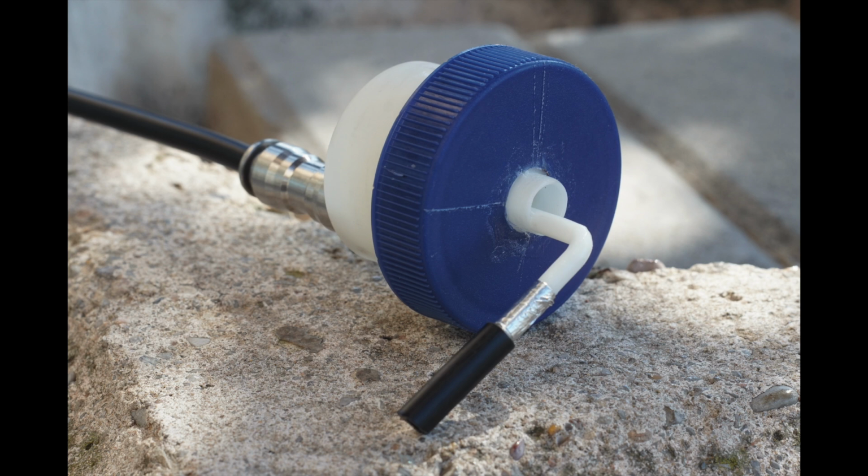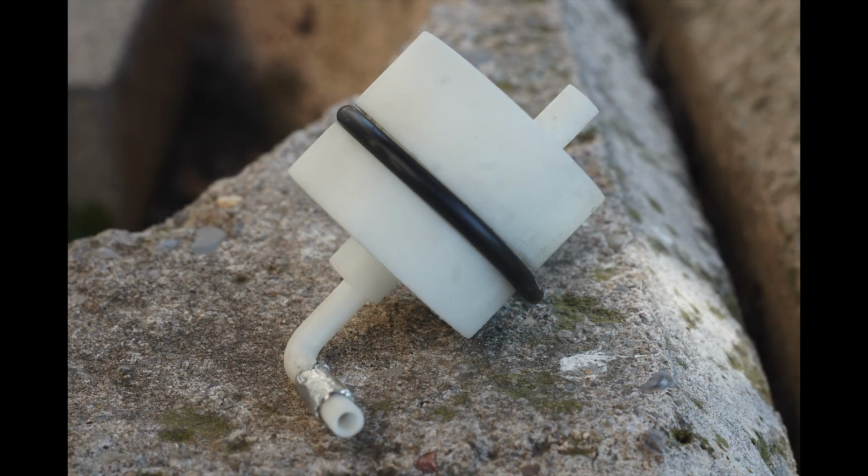Its precision allowed us to include an internal duct for air pressure equalization without concerns about overhangs. It also provided a smoother surface finish, though this has little effect in laminar flows. Our final design includes a tube connected via a 6 mm pneumatic fitting to reduce the air spring effect.